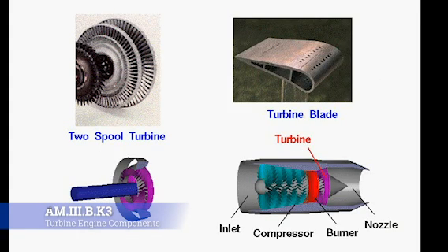Okay, so now once we are through the combustion section, we're going to get into the turbine section. This is where all this work that's happened to the air and the fuel is really going to start to get harvested. We're going to start to see the benefit of it, because as that hot gas leaves the combustion section, it's going to flow over these turbine blades, and as it goes over the turbine blades, they're naturally going to want to spin because of Bernoulli's principle, as you know, they're shaped like airfoils. The low pressure area on top of the airfoil is going to give way to the higher pressure area on the bottom of the airfoil and cause it to go up.